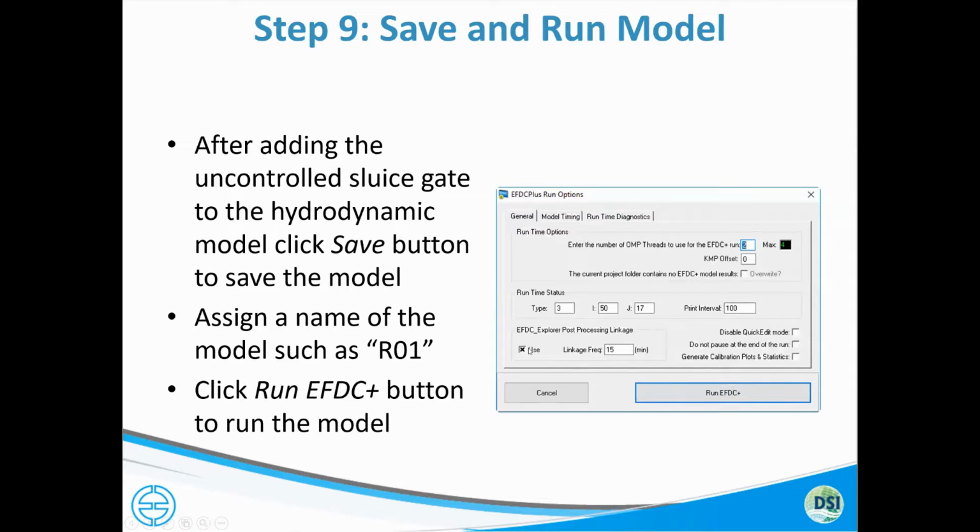And here we're telling it we're going to use post-processing, but in the prior slide, you saw that 60-minute frequency. Anything that you enter under this form before you press run overwrites what may have been in the prior form. So this is just your last chance to make any final adjustments to the inputs before you actually run the model.